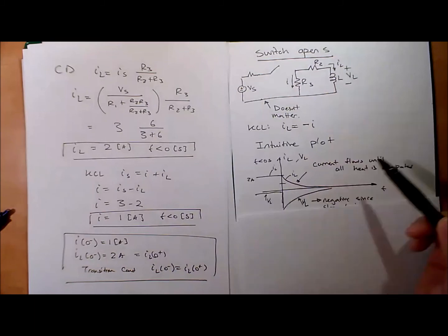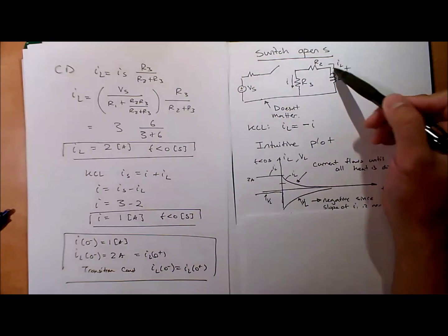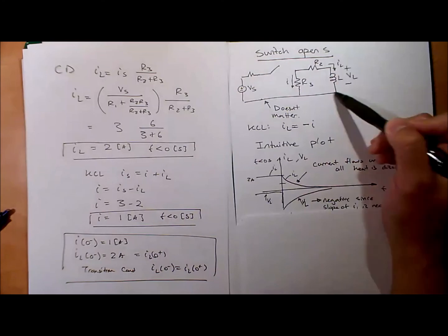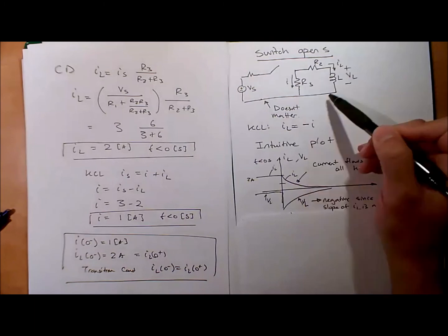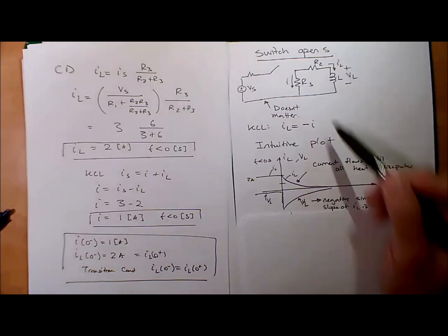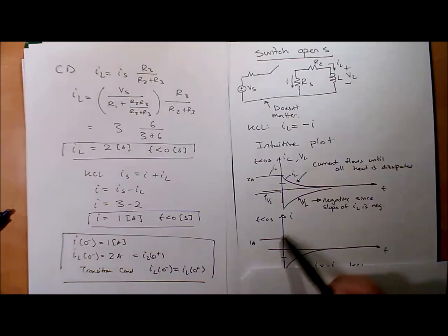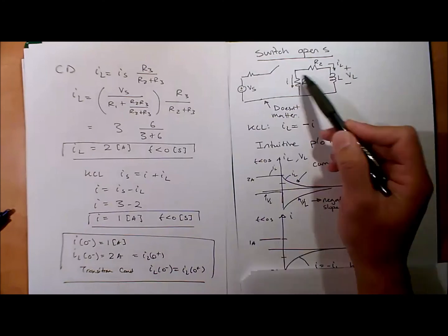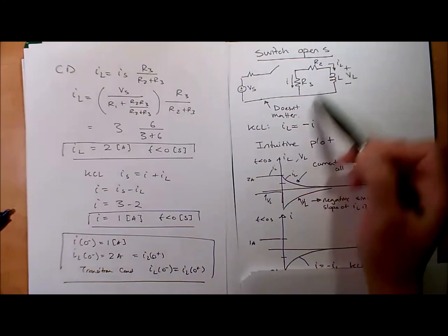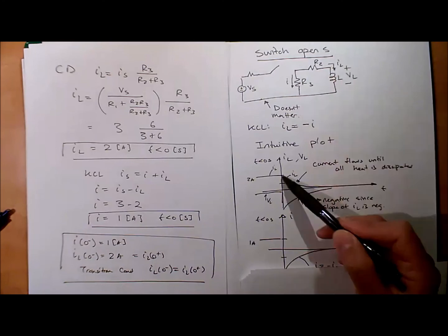Okay, what about the voltage? Voltage is going to be 0. All of a sudden, bang, it pops here, and then applies that pressure to keep that going, but then also spools down. The current in here is going to be initially 1, but what is this current going to do? It's 1, and then immediately after this opens, well, by KCL, I equals negative IL. It's just the opposite of this.